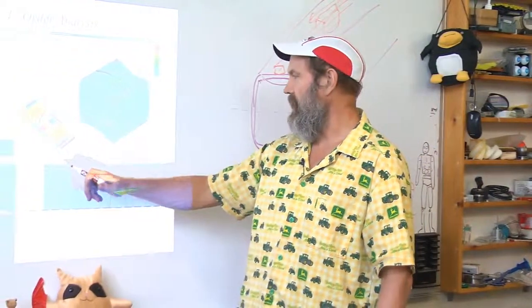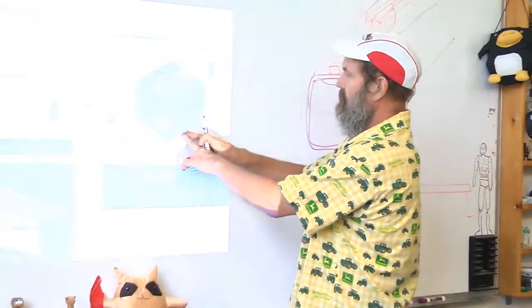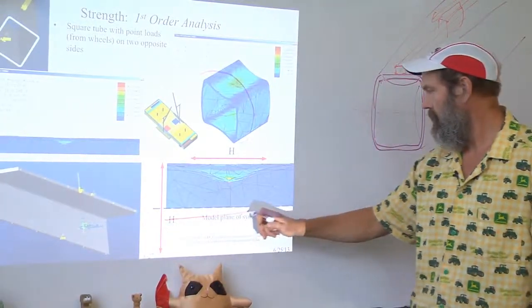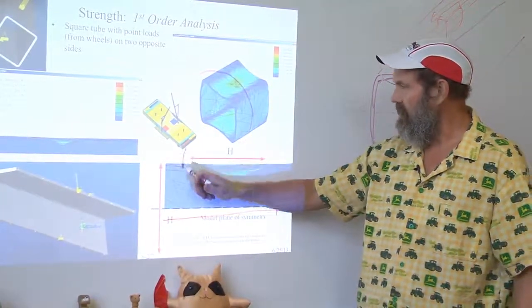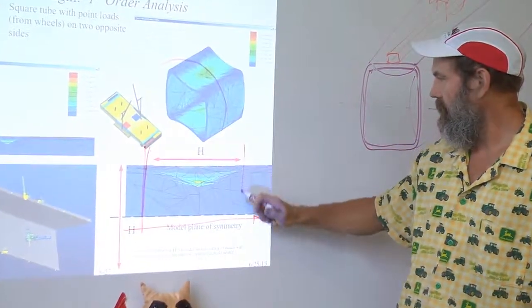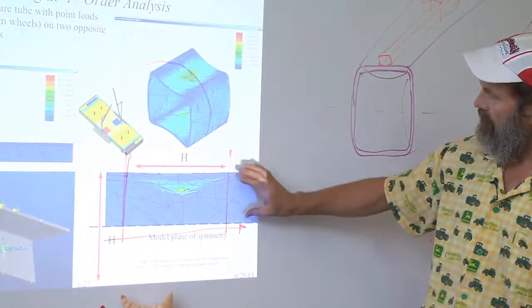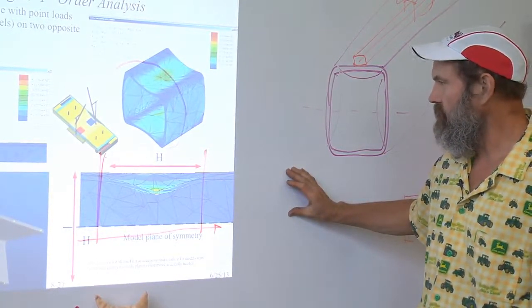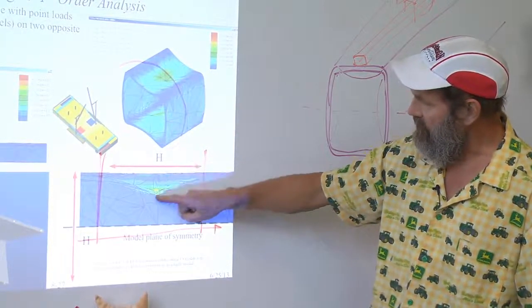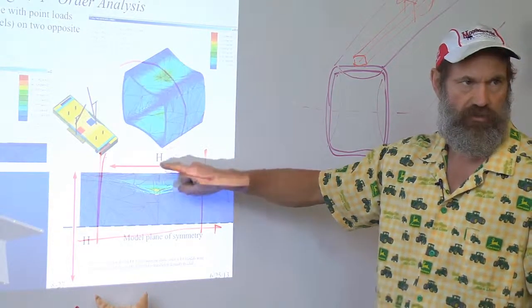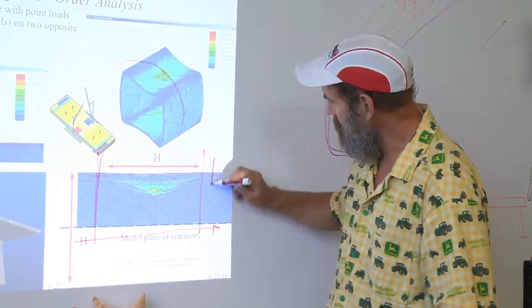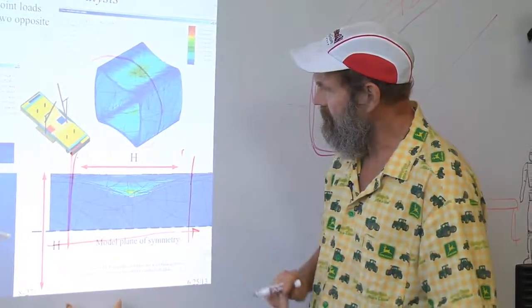For example, this is taking this structure and in a finite element model, gradually increasing the length until you see we get to a point where making it longer doesn't really do much with respect to predicting the deflection here or the strength. Huh, that's interesting. And I guess it actually starts about here.